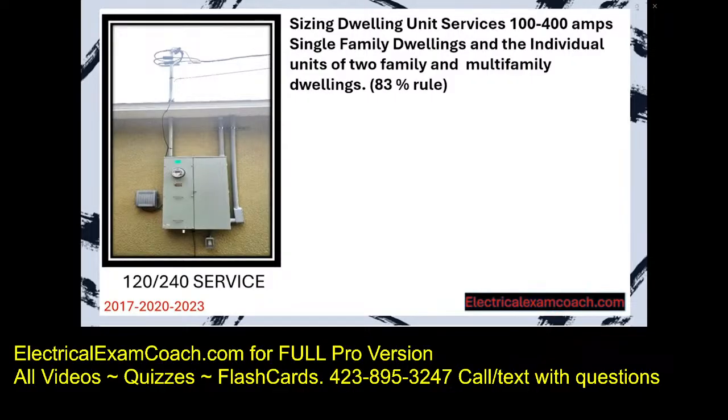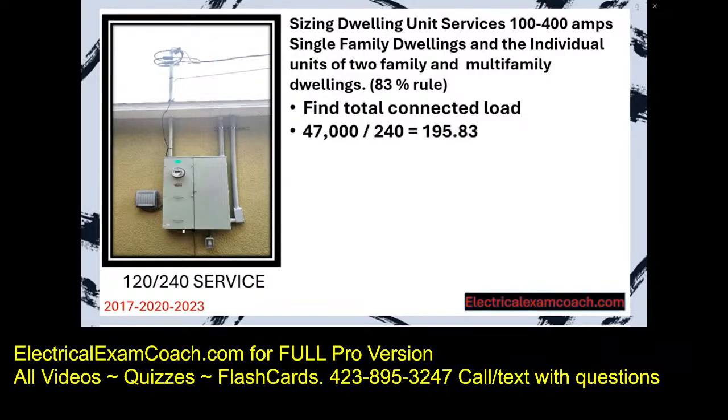Let's imagine that we have a dwelling, and the first thing we're going to do is find our total connected load. Let's imagine that it's 47,000 VAs on a 240 volt system. That gives us 195.83. We would round up to 196 and go size our main breaker. And the main breaker would be a 200. That's the next standard size. We now have a 200 amp service.